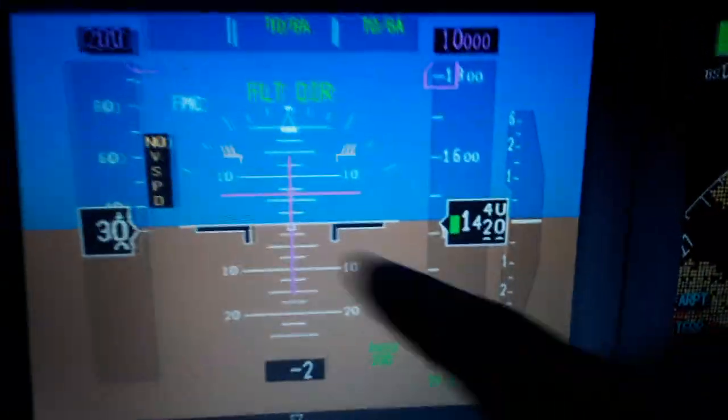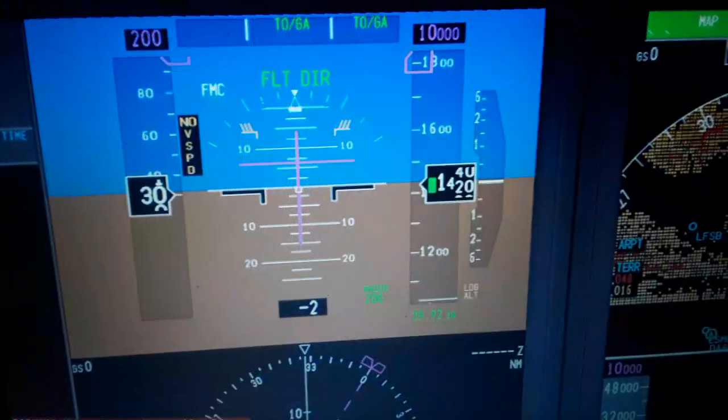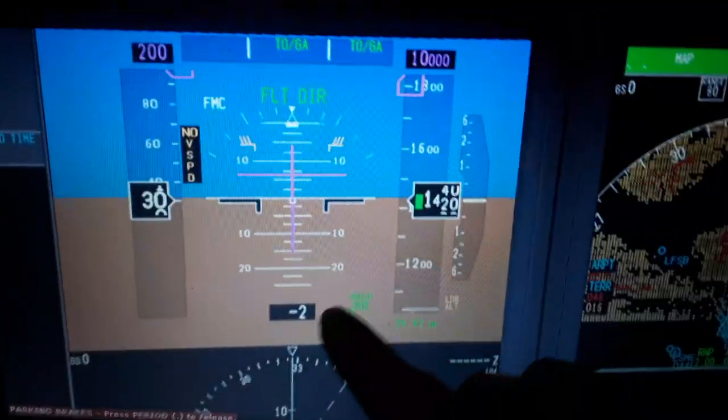So you can see here we have the primary flight display. You can see we have the airspeed indicator here, the airspeed tape, the airspeed selected from the autopilot flight director system panel. The ground speed is displayed here in the navigation display. The radio altitude above the ground level, you can display up to 2,500 feet over here when flying above the ground also.